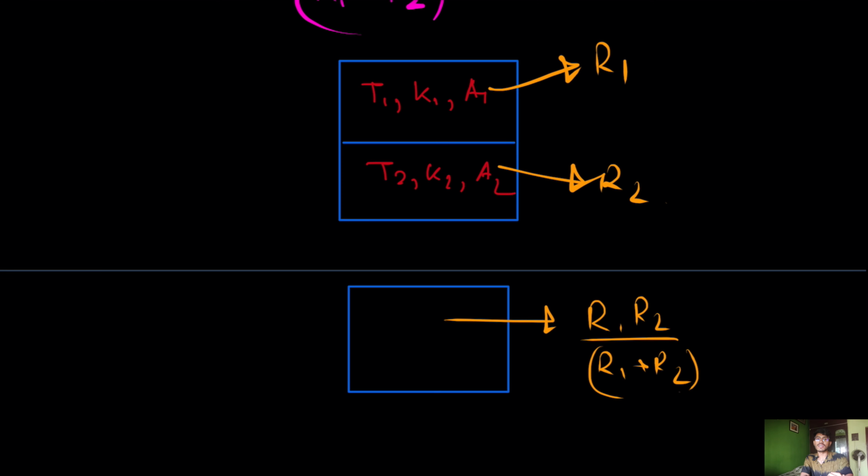There the voltage difference is analogous to the pressure difference, there is hydraulic resistance instead of thermal resistance or electrical resistance, and there is the fluid flow rate instead of current. So this analogy is very useful because we all have read this electrical network during our secondary and higher secondary studies, and we take that advantage in the higher level courses.